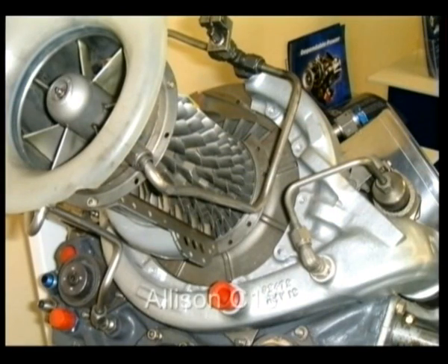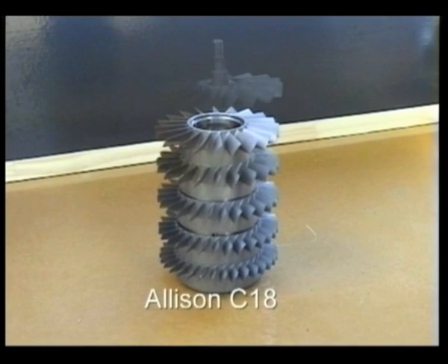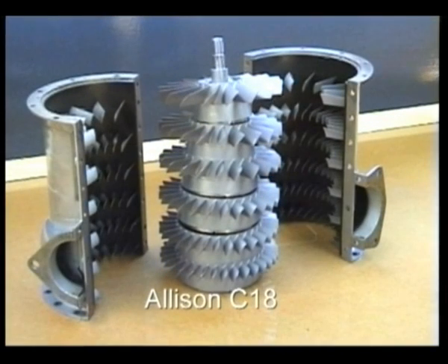Every compressor design is a compromise between achieving high performance over a narrow RPM band or moderate performance over a wide RPM band. Each ring of blades and its associated fixed stator vanes is called a stage, so that the air alternately passes between rotor blades and stator vanes. Without the stators, the air would just be driven round and round by the moving blades to no effect. Each stage makes the air a little more compressed and also a little hotter, and its volume is reduced.